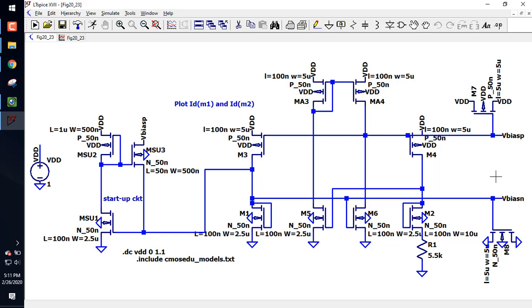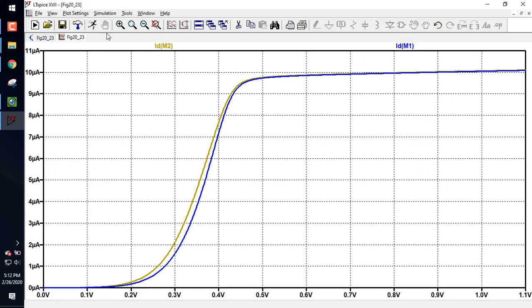So what I'm going to do, I put this capacitor here on the output of the amplifier. So here's the output of the amplifier. I put this capacitor here, and now I'm going to remove that and see what happens. So I'm going to axe that. This one's not in, this is on an input, so I don't think this one matters. I'm going to hit run. So now I don't have that capacitor slowing things down. Oh, maybe it does matter.